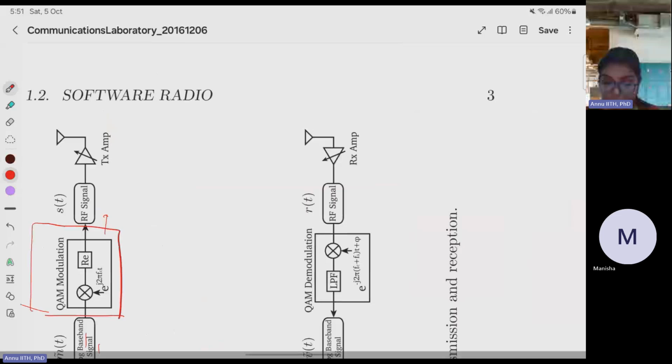So a software-defined radio can be defined as a radio in which some or all of the physical layer functions are implemented through modifiable software operating on programmable processing technology. A conventional hardware-based radio device provides operational flexibility only by physically changing the hardware components. In contrast, software-defined radio provides an inexpensive multi-mode, multi-function, multi-protocol device that can be modified using software upgrades.